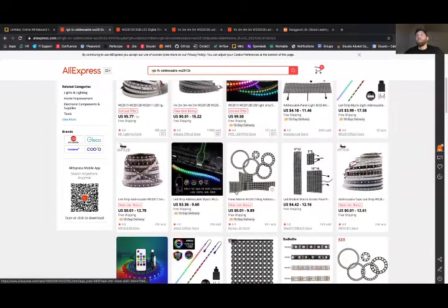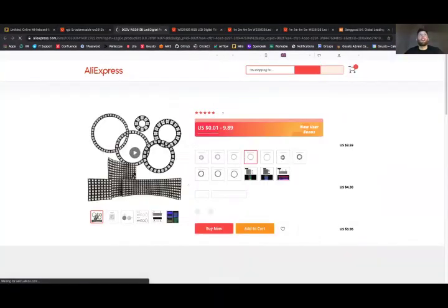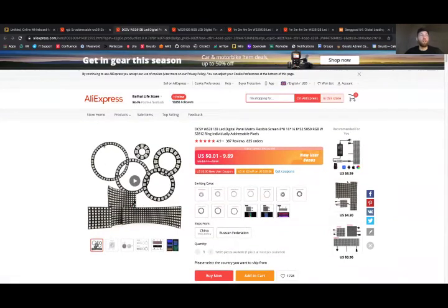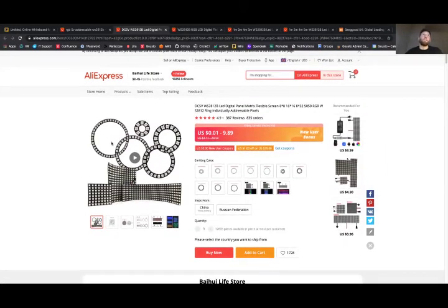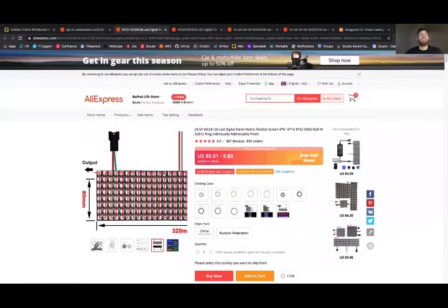And then there are some funkier form factors like these rings. The rings are quite nice. They're very delicate, very sort of elegantly spaced. They're very beautiful. These actually come on a hard PCB, so that's another option that we haven't discussed, hard PCB versus flex PCB. Flex PCB, you can bend around corners like you see in this panel here, but the rings come on hard PCB, so something to think about. These rings are quite good for sewing into clothing, as an interesting side note.